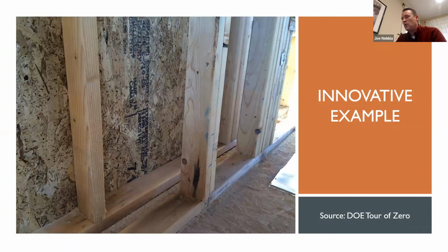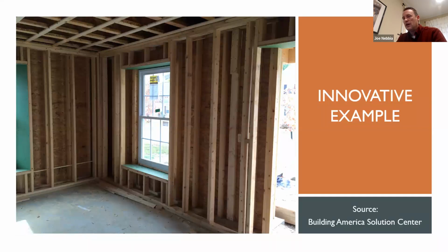This is a picture of a double wall. You'll see here, these are two 2x4 walls with a gap in between, and this wall will be filled with insulation, with blown in usually. That means the gap in between those two walls will be filled with insulation and will essentially be creating a continuous insulation barrier or layer in between those two filled 2x4 walls.